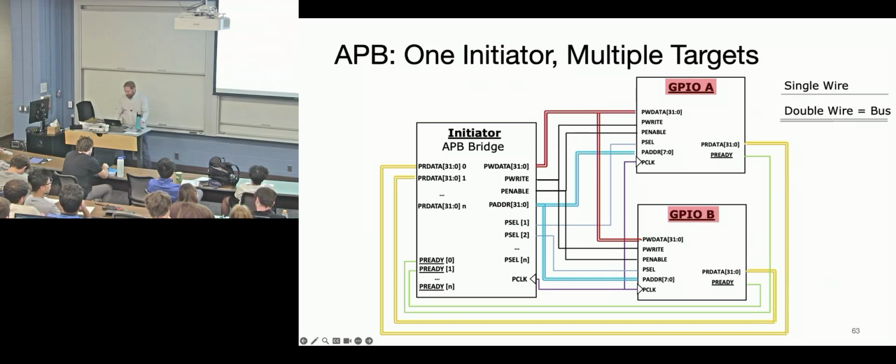Let's see. I see a lull in questions, so I'll try and teach this last little bit. It's important to remember conceptually that there are different peripherals, and remember peripherals each have their own P-select. But in any individual peripheral, there could be multiple registers with multiple addresses. It could be hundreds of registers in a peripheral. So that's why you really need to keep track of the address.